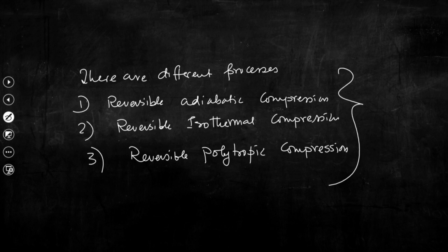So, these three are the possibilities. The compression process can be performed assuming the process is reversible adiabatic. The compression process can be executed assuming the process is reversible isothermal, but an isothermal compression is very difficult to achieve.